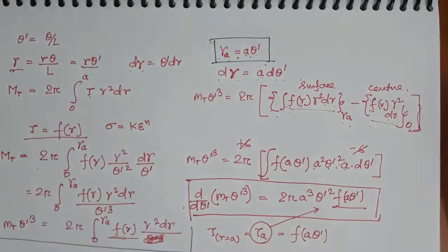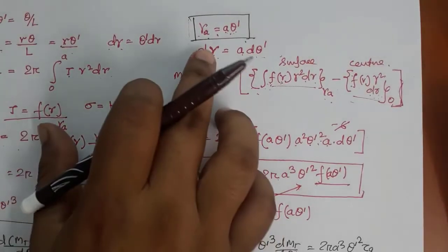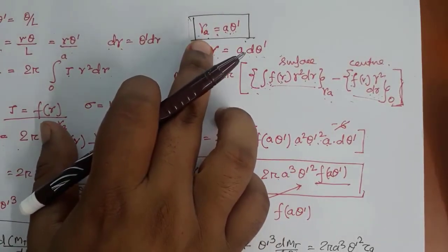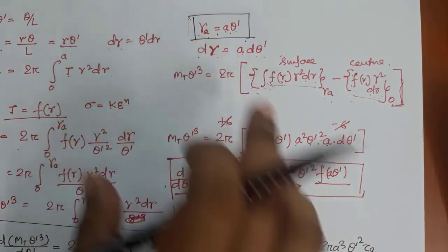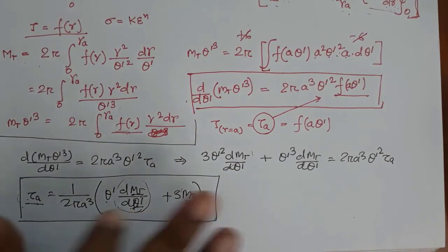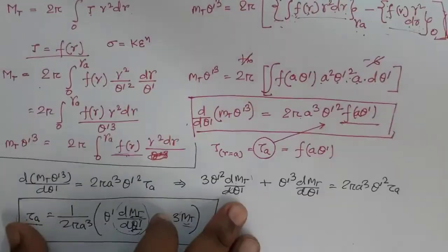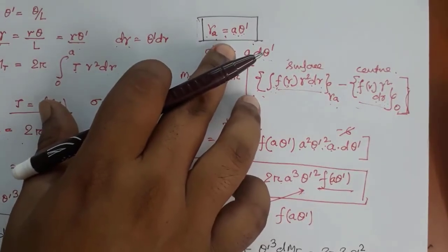Okay. So, we are getting shear stress from this equation and we are getting shear strain from that equation. So, what we are essentially doing is measuring the torsional moment and angle of twist, and from that we are calculating shear stress and shear strain. Okay.